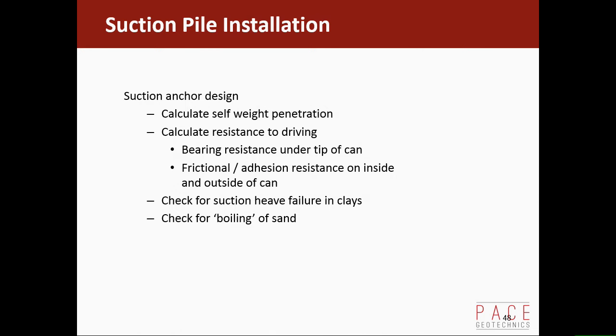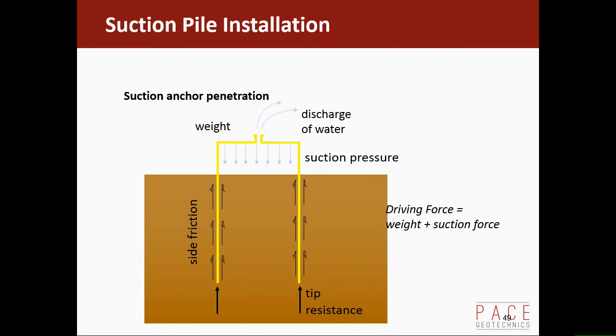So the installation process or design is calculate the self-weight penetration of the pile, calculate the resistance of driving it to depth, and the process is the end bearing resistance and adhesion of the pile. This is exactly the same as with a driven pile. We will check for suction heave as the pile goes in. This is the diagram of the sort of stresses on the pile, the forces. So you've got friction on the inside and outside, and tip resistance.